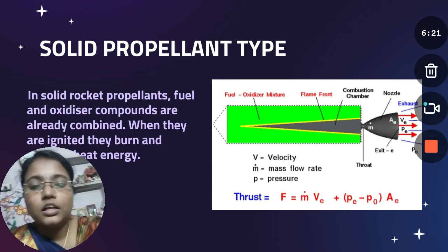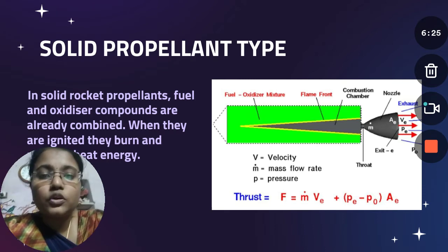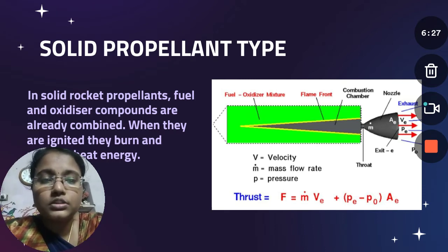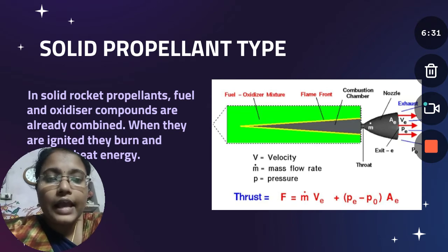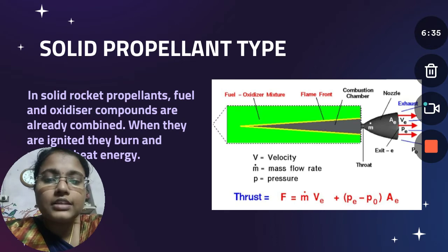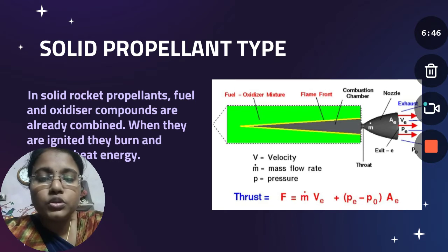A double base propellant consists of nitrocellulose with nitroglycerin or other liquid organic nitrate explosive added. Stabilizer and other additives are also used. Nitroglycerin reduces smoke and increases the energy output. Double base propellants are used in rockets, cannons and small arms.